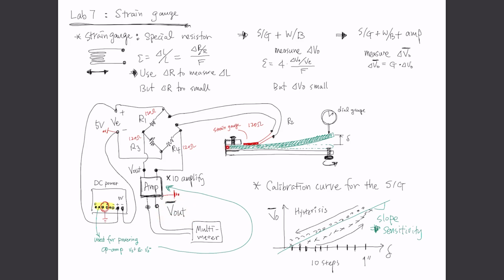And so this strain gauge is being attached to a cantilever beam that you see here, and you are using a screw to secure it so that it becomes affixed on one side. And on the other side, you have another screw, so you are rotating this, and this is pushing the beam up and up and up like that, and you are measuring that using the dial gauge, okay? So from here you can measure the displacement in this direction.